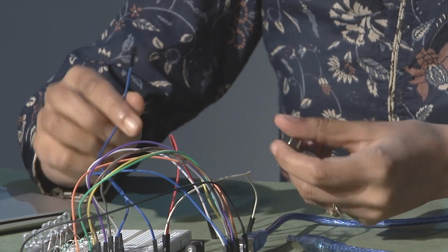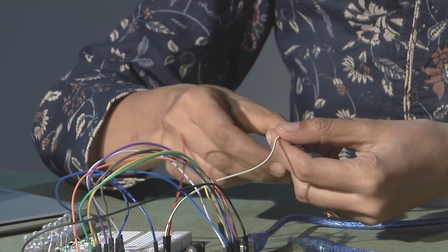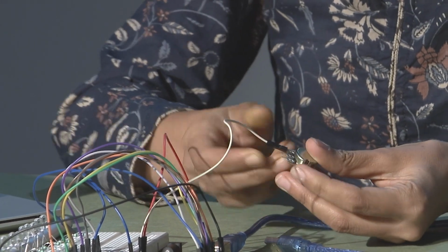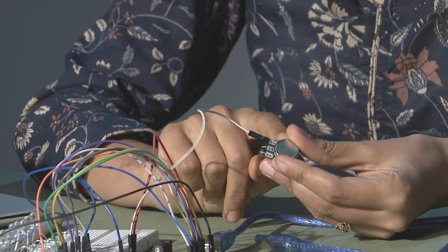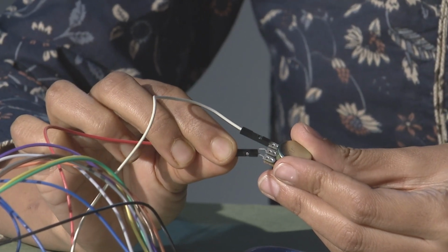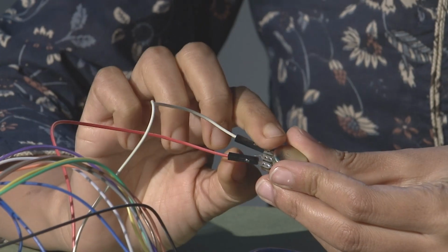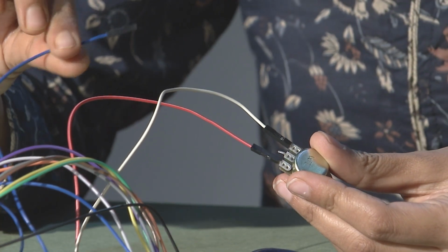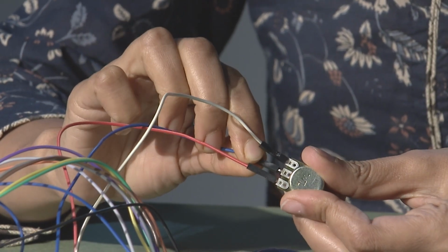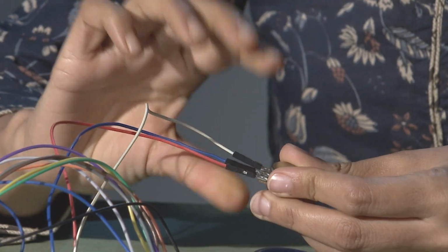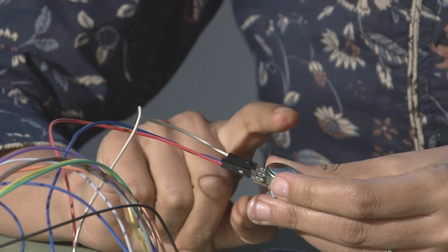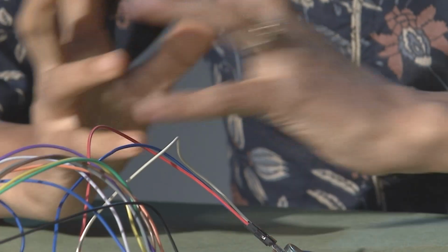So, first of all, let me make connections for your pot. First we have the ground terminal, so let me choose one of the terminals from the extreme end as ground. The other extreme end terminal I can choose as the VCC terminal, and similarly one analog terminal on the wiper. So, these are the 3 important connections on the hardware side. Based on this, now we need to check the code.